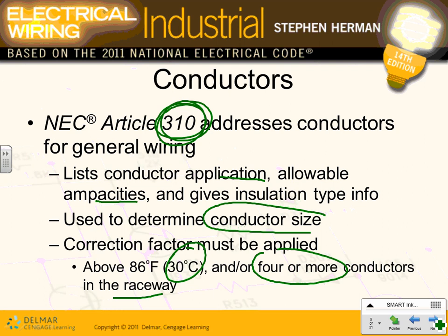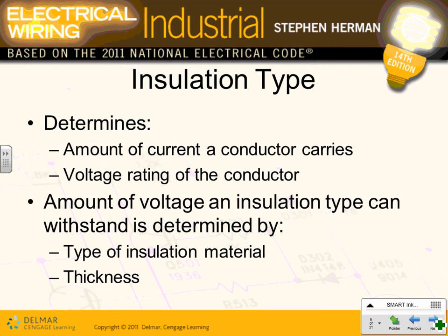If you don't know that, I hope, guys, this is your last semester with us. We did 2 projects already. I really do hope that we did some with Gary. You understand that everything is related to the conductors in Article 310, which gives you the ampacity of the conductor plus the ability to derate based on bundling, more than 3 conductors, or based on temperature, or both.